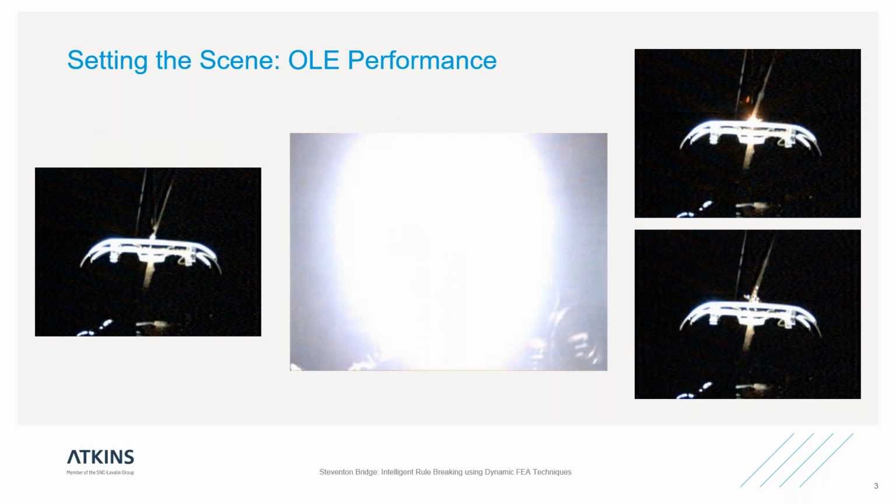So a couple of slides first to bring everybody up to speed on OLE performance. The thing that overhead line engineers worry about more than anything else is the dynamic behavior at the point where the pantograph meets the contact wire. And for electric trains to work well, for the system to remain undamaged, there needs to be continuous contact between the pantograph and the wire.